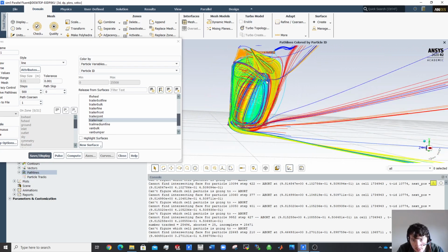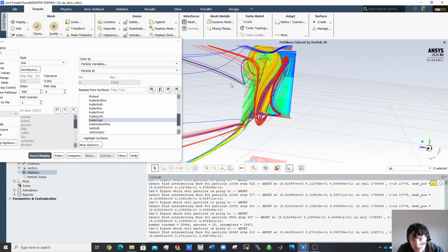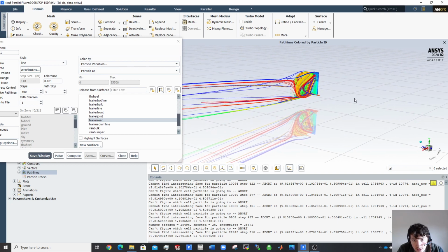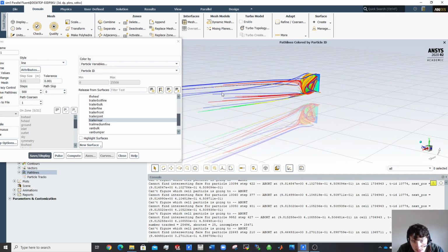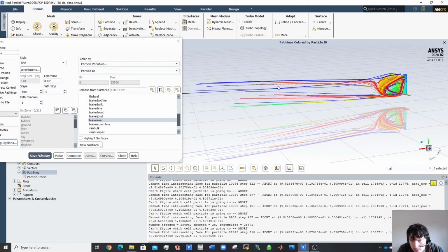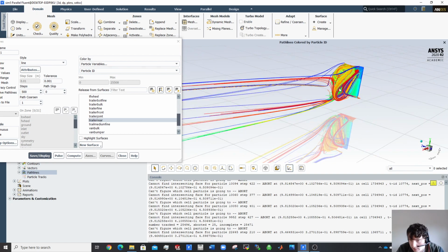This is very variable, but this just gives you an idea of what it was for that split second, how crazy the wake was, and how the lines move down from it. So you can see when these start to straighten out. You can make these longer as well by increasing your step size and your number of steps. Usually you might multiply those two numbers together to get an idea of how many meters you're coming down here. So that's the length of the streamline.